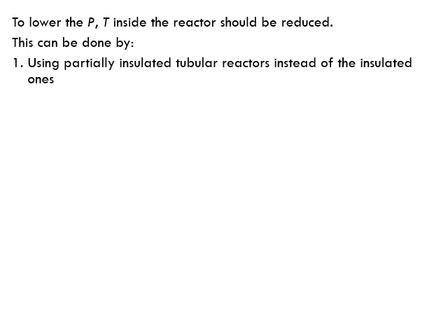So we had an insulated reactor, and the reactor was operating adiabatically. The released heat from the reaction was staying within the reactor, therefore the temperature was increasing a lot. So what about using a partially insulated one? This way, part of the released heat from the reaction can leave the system, and therefore we can maintain lower temperature. That's one solution.